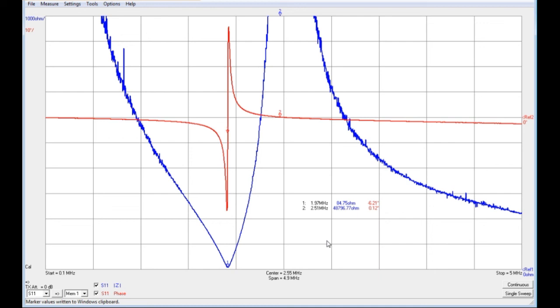See how much difference that makes now when we just look at the coil itself. This gives us quite a clear indication of how that actually resonates. And we look at the impedance, 84.75 ohms at that resonance dip. Obviously we're sitting on the 50 ohms. This is a series fed measurement. The 50 ohm output impedance goes between ground and the top there. So that is a series fed measurement, and we can measure any of the coils like that.